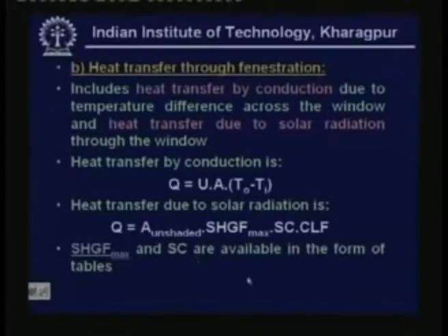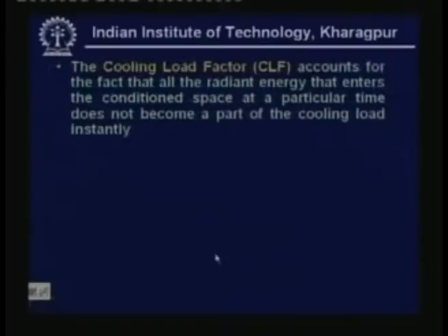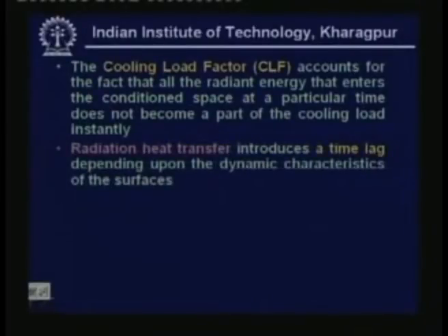Then what is cooling load factor? The cooling load factor CLF accounts for the fact that all the radiant energy that enters the conditioned space at a particular time does not become a part of the cooling load instantly. Radiation heat transfer introduces time lag depending upon the dynamic characteristics of the surface.